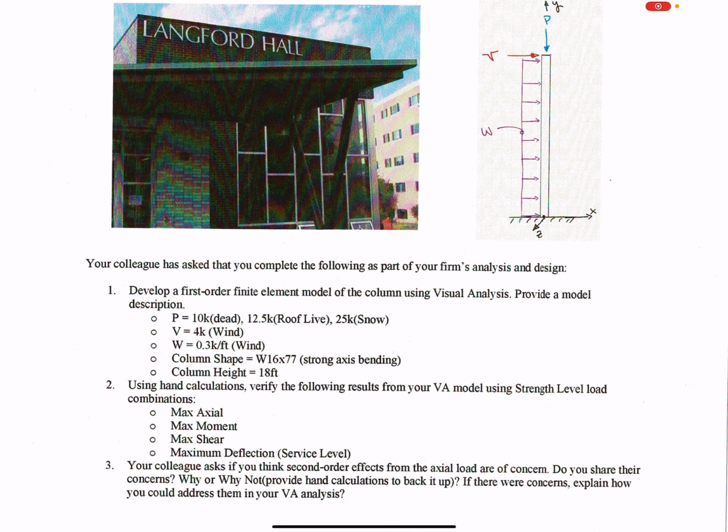Back to ASD, or allowable stress load combinations, where we're not trying to increase the demands and decrease capacity, which we do with LRFD. We're manipulating both sides of the equation with LRFD. For ASD, we're just manipulating the capacity side. You have an allowable stress. How many of you took wood? So you did ASD for wood design. Masonry, ASD for masonry design. In all of those, you're calculating a demand based on ASD combinations and relating that back to an allowable stress.